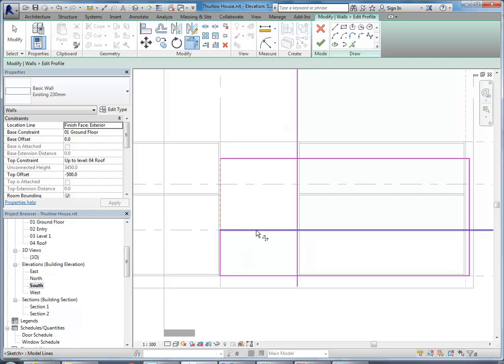Okay, and so this line here at the bottom, the line on the edge of the wall, yep, at the bottom. So you need to be on Trim to Corner, next to Rotate. Yep, and then the one above and to the right. Yep, and then choose that line again, and then again the line above and to the right. So this line here, and then the vertical line above and to the right, and then that line again, and then again above and to the right. So basically you've got an L shape. Okay, so if that's worked for you, tick to finish.